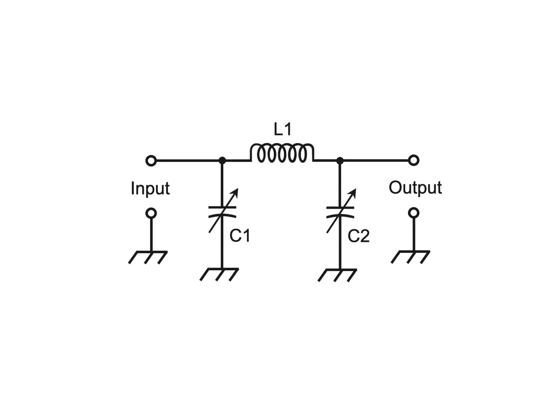This is another type of antenna matching network, which consists of a circuit we have seen before, with an extra capacitor added at the input end. Engineers sometimes call this type of circuit a pi network because its components, in the schematic layout, resemble the shape of the uppercase Greek letter pi. Both the L network and the Pi network are commonly used in antenna tuning and matching circuits for radio transmitters at frequencies ranging up to around 150 MHz.